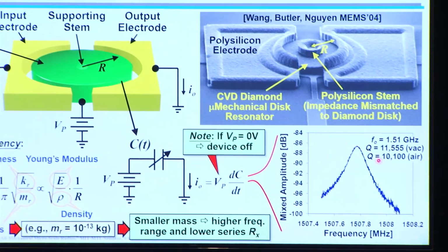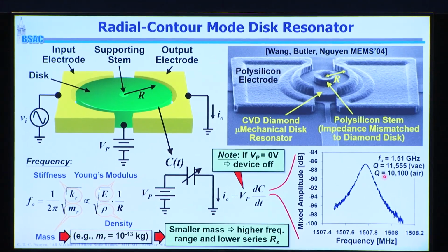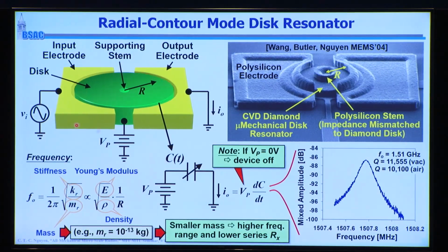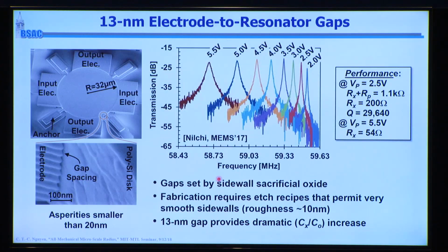And the nice thing about this as well is I can turn this resonator, an eventual filter, on and off at will. So it's kind of like an LCR tank circuit, but if I make the bias voltage on the device 0, I'll get no current out, which effectively means I've shut it off. It's almost like a transistor, LCR, and one device. It's a very nice device to be able to play with at the front end of a communication system.